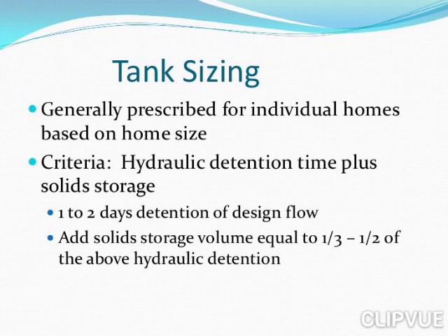Now details about the sizing of the tank. Generally it's prescribed for individual homes based on the home size. The criteria says that the hydraulic detention time plus solid storage varies from 1 to 2 days of detention time of the total design flow, and it adds solid storage volume which is equal to 1/3 to half of the above hydraulic detention.